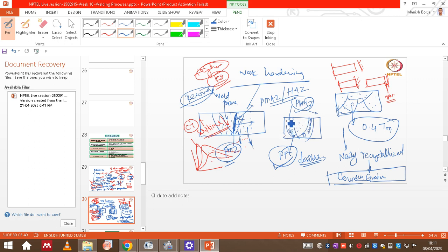But in certain cases the metal near the boundary of this fusion zone, which is the heat affected zone, their precipitates simply coarsen. They won't completely melt. If they coarsen, there won't be extra solute available for renucleation, right? So again post-weld heat treatment is not effective in such cases.